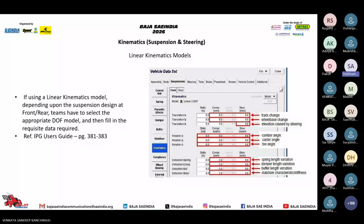In that, the team first needs to go into the kinematics, and there they need to select, if the teams are new teams and they don't know how to get those coordinates from their vehicle CAD model and how to input those, simply go into the kinematics front part and select linear 2DF. Over there, in the user guide or the guidelines, this diagram is mentioned. You must have calculated these values while designing the suspension in your real-life car model. Just input those values. The static value will for sure be 0, 0. There will be no changes.